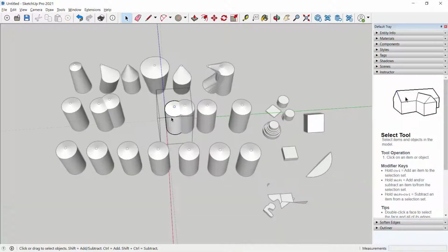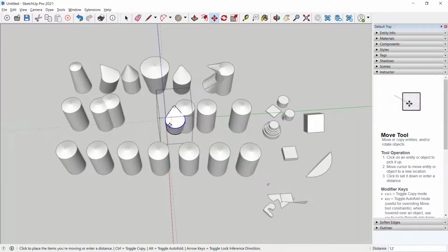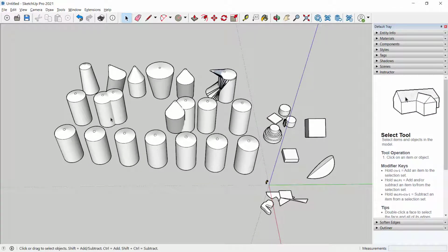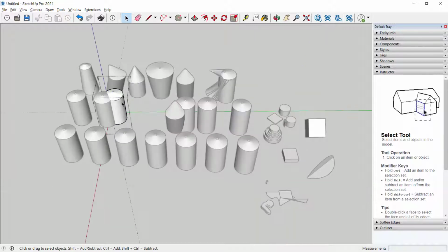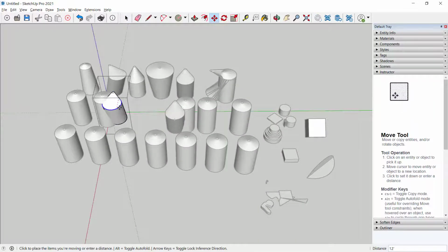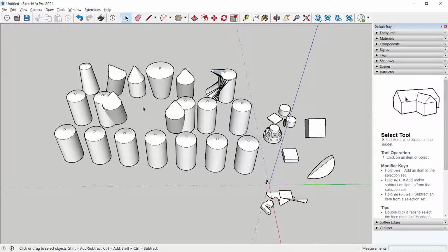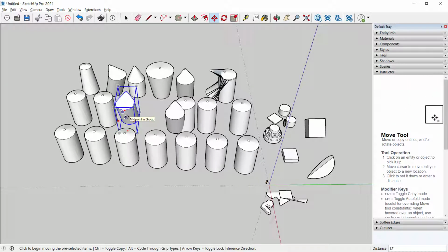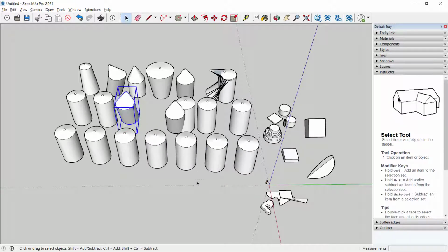You can still edit them. I can come in and make funny shapes out of each one, and it will not affect the others, but I have to take that extra step of double-clicking on the object in order to make changes. And it means that the geometry remains independent. I can move these apart or together if I want. And this is great for one-off items such as interior partitions, or things like furniture elements, which you don't want to stick to each other. You want to be able to move them independently.